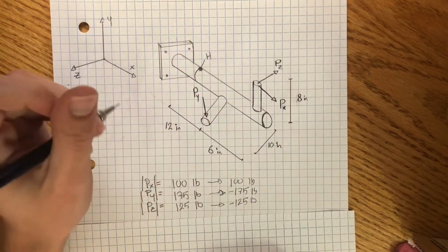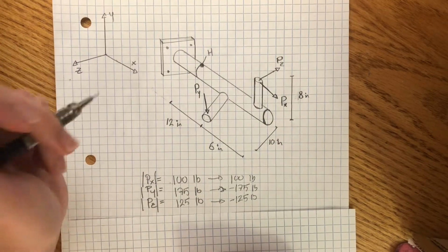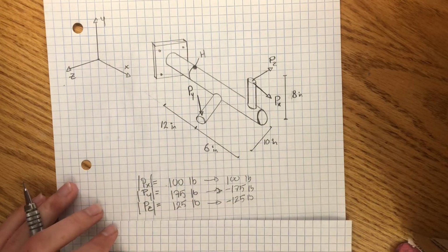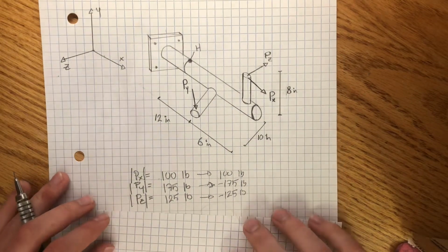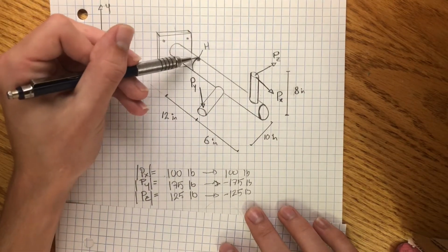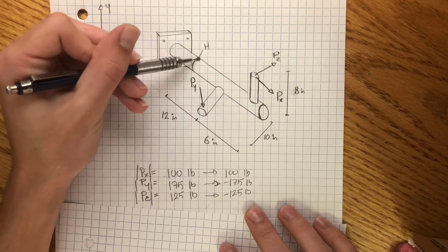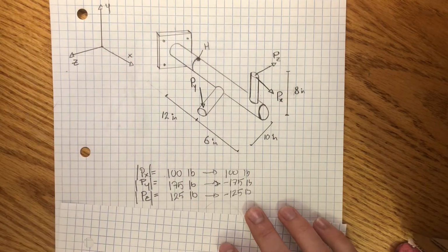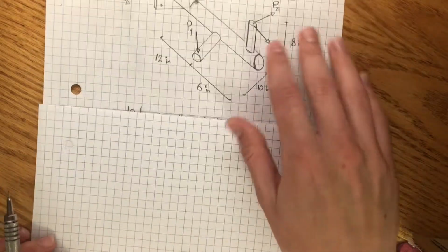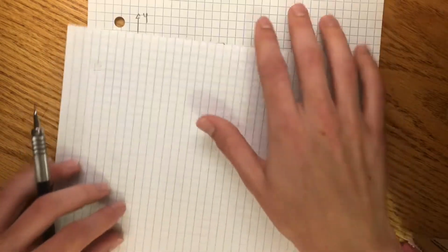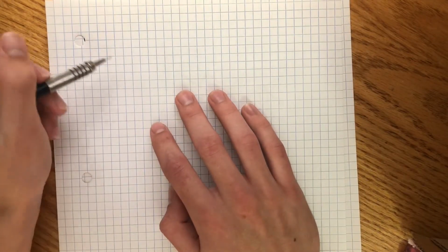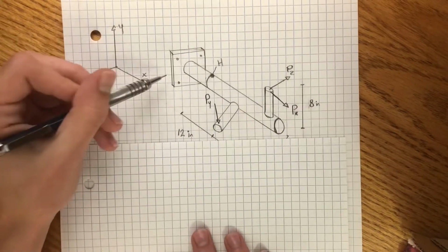And what we want to do essentially is create a free body diagram, kind of like we would in statics, and use that to help us find all of the reactions and moments that are in this specific cross section here that our point of interest is on. So the way we do that is, we know that this thing is in equilibrium, and we know it's fixed at that back end there.